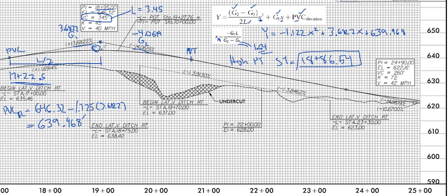Another thing, we should also have some idea before we start calculating the elevation, we can read off this design plan approximately what it is. And it looks like we're somewhere in the range of 643. And so I'm going to expect some value around 643. If I don't get something there, I probably made a mistake with the math, and I'm going to take a closer look and see where I went wrong.